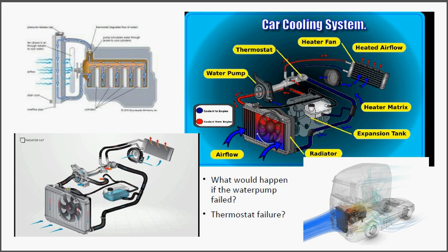But a quick check before and after the thermostat will tell you whether it's working or not. If it's working, the temperatures should be very equal. Otherwise, one side is really cold and the other side is really hot. So there's quite a difference, and that's an indicator that your thermostat has gone. It's not a great job.